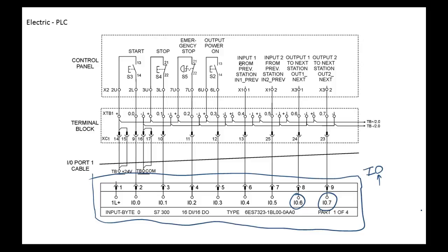The Allen Bradley modules can run in groups of 16s. So that means I can buy a module that has 32 inputs, but it would take up 2 module numbers. Does that make sense? The Siemens runs in groups of 8s. So the first group module would be 0 to 7. The next one would be what? Yeah, 8 to 15. We can see that when you look at that.